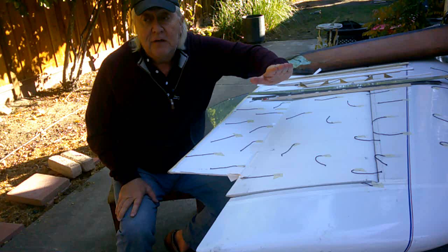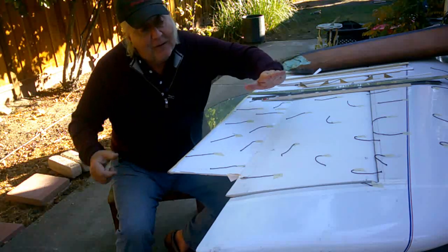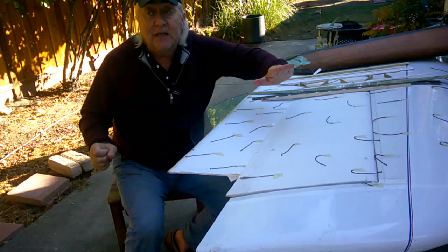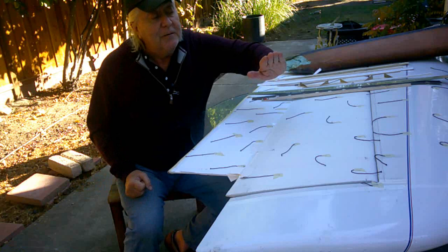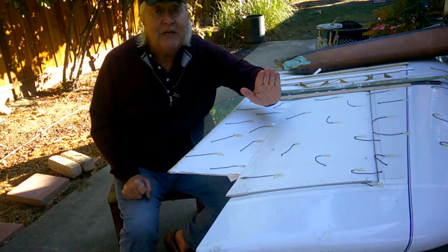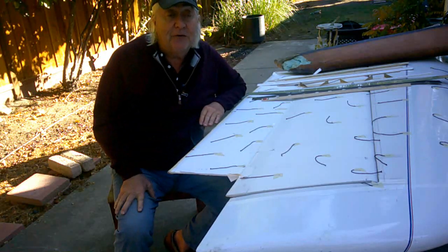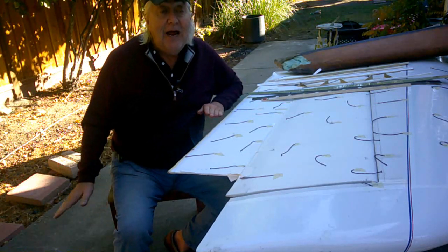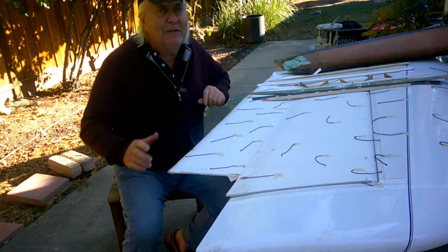So what does the pilot do? Oh, I'm not rolling fast enough. He doesn't stop to think, oh, the flow is separating out on the elevon. He's like, I'm not rolling fast enough, not rolling. So you put in more right stick. Put the elevon even further down. Oh, and the flow separates even more, the problem gets worse. And then you really get separated flow, you get a massive amount of drag, you get adverse yaw, and you start to actually point the nose opposite of the way that you want to go.